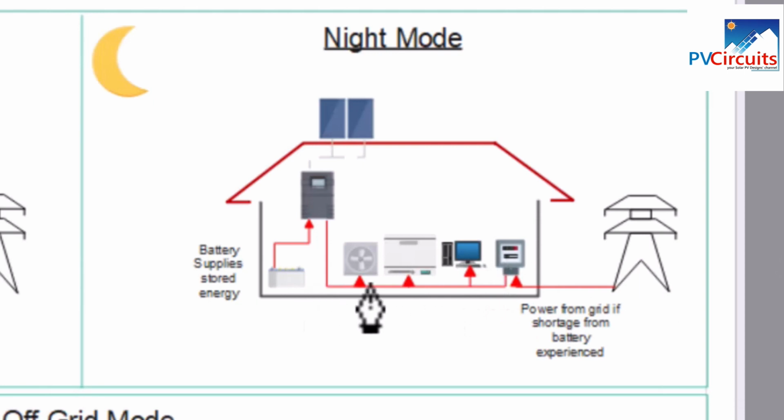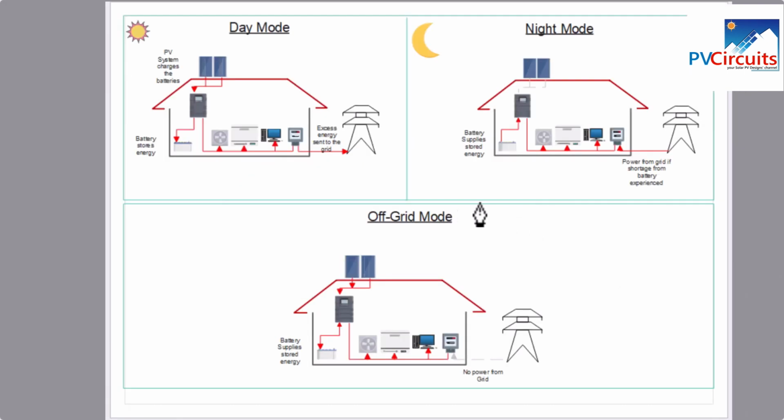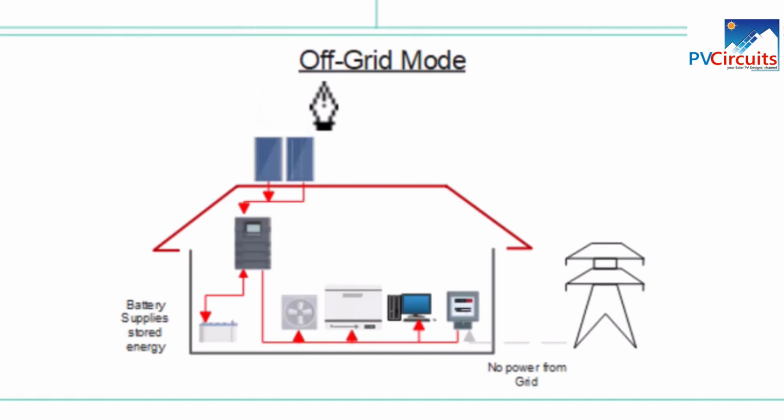We can set the hybrid system to off-grid mode, and what happens in off-grid mode is the grid is not connected, so the only power comes from the PV. This is during the day, and it charges the battery, and there is interaction back and forth just to make sure that if there's more power required by the household consumers, then the battery can meet that shortfall.